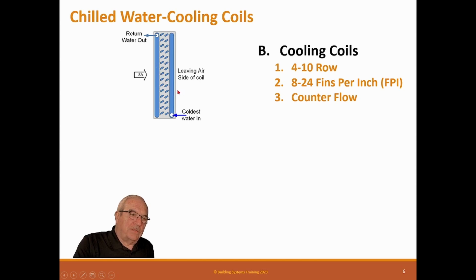The problem is this is not the coldest water. This is return water temperature. So this will be up here slightly, and what happens is this doesn't dehumidify. But you want the coldest water here. So if you have the coldest water coming in here, it drops it. The air leaving is almost just a few degrees higher than the actual water temperature, and it will actually dehumidify more. So that's really important in chill water coils. I always told my people just make sure all coils are counterflow, then you'll never make a mistake. Counterflow. So critical to coil performance.